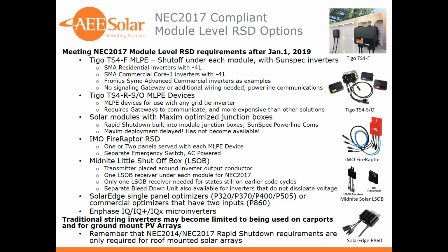So what solutions do we have to comply with NEC 2017? So, module level options that we have. The one that has had most interest is using the Tigo TS4-F MLPE shutdown device. So that is a box placed under each module. The advantage here is that it's using the new SunSpec